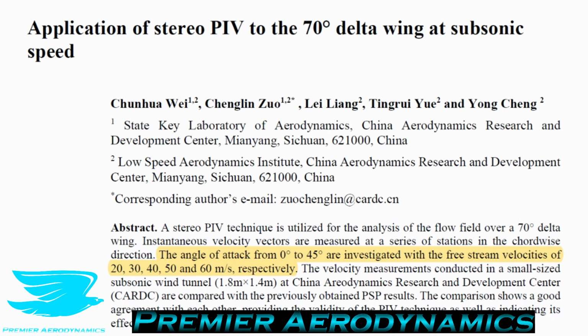And PIV can be used in a transient motion fashion. So if you have a very high shutter rate, you can actually get kilohertz resolution. The temporal resolution is really good. So that's regular PIV. But as I mentioned, you do have the problem sometimes of getting corruption in the velocities. And that's because of the third component. Regular PIV just looks at two components, but you do get that third component which does corrupt the results. Stereo PIV is designed to get rid of that problem.